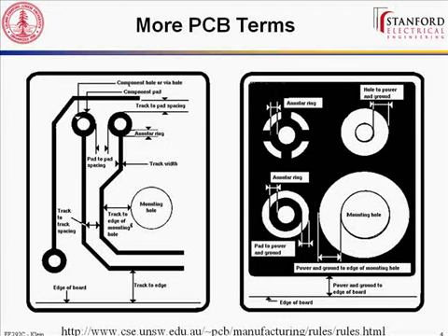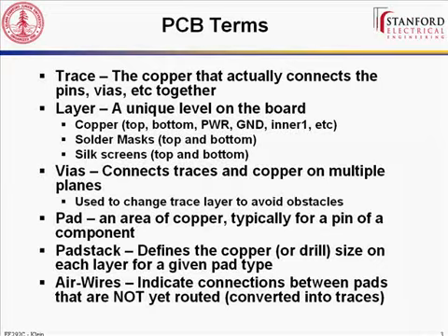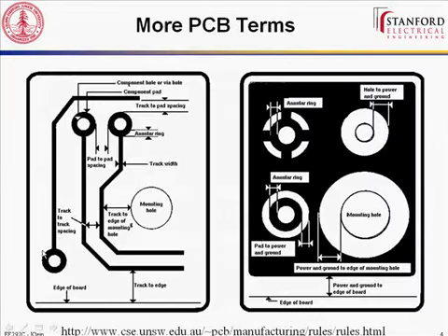So any other questions on these terms? Yeah? Why do we need that copper layer in the bottom left? Is it the annular ring? The copper layer here? No, on the right. Oh, here? Yeah. So you're required to have an annular ring around every hole that's plated.